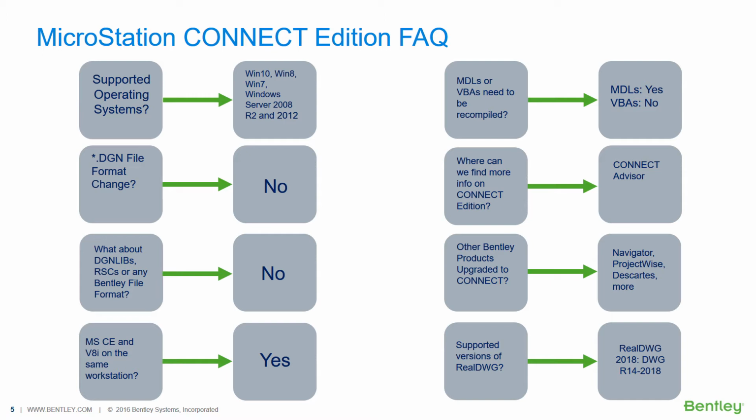MDLs, which were written in C or C++, will need to be recompiled because the 64-bit graphics engine of MicroStation requires that those particular applications be recompiled as 64-bit applications. So we do have courses available. We do have a lot of help available from our development teams. So if you're interested in finding out more about MDLs, please feel free to contact us, and we'll be happy to help there.